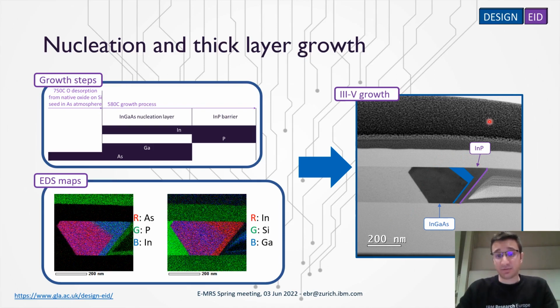However, during the growth of the indium phosphide layer, the material grows quickly in the 110 direction, extinguishing the corresponding facets, and stabilizing, as a result, a single facet for the growth front, the 111 facet.